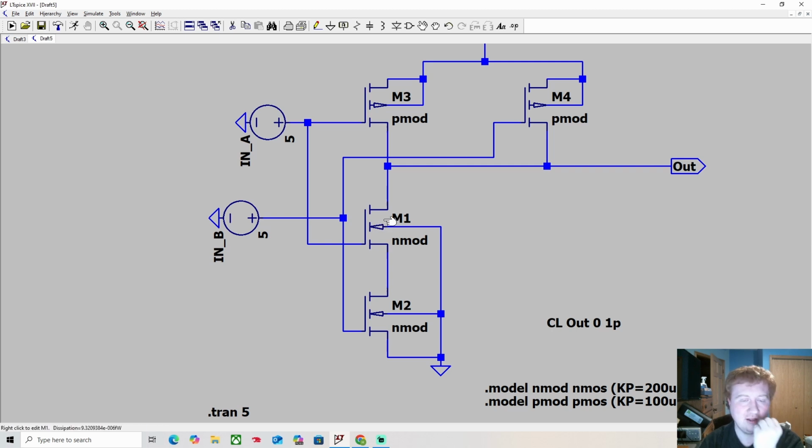In a low side configured MOSFET, if the gate is higher than the source, it will turn on, like a normally open switch, if you flick it on, it'll make close contact and make a circuit complete.